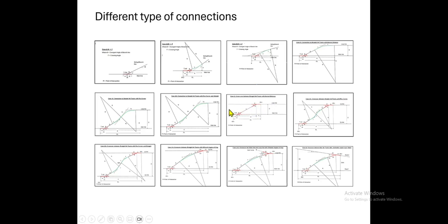Here we need to provide two points and crossings, on both lines. So for normal distance, we don't provide any curve in between, just straight connections. When we are providing straight connections, how should it be designed? In case of the same crossover with a large distance, slightly more, some 20 meters, if we are providing a straight connection, what will happen? The overall length will become more.